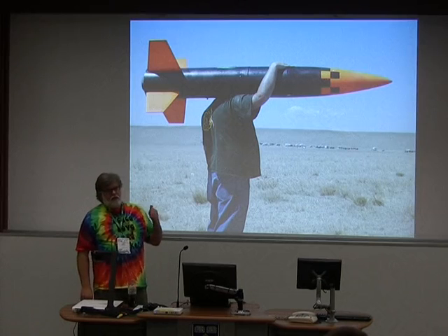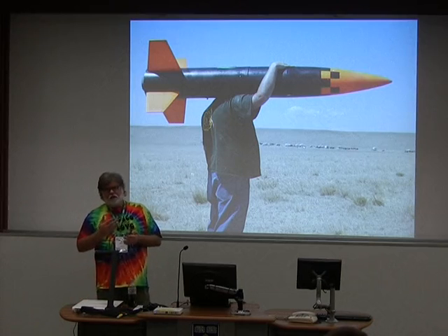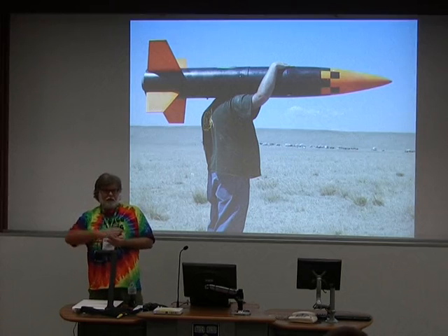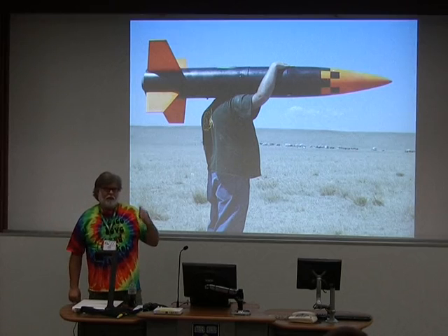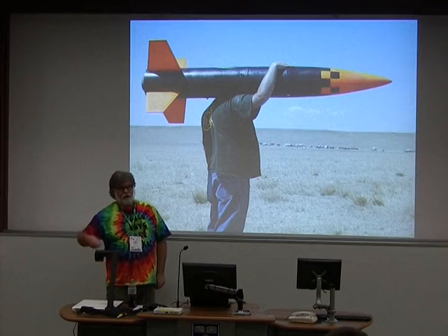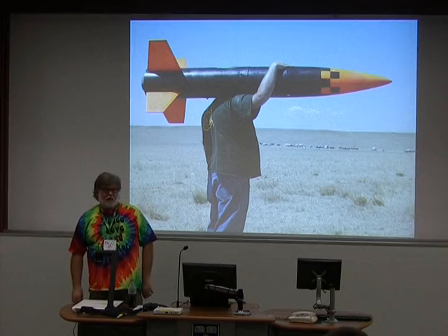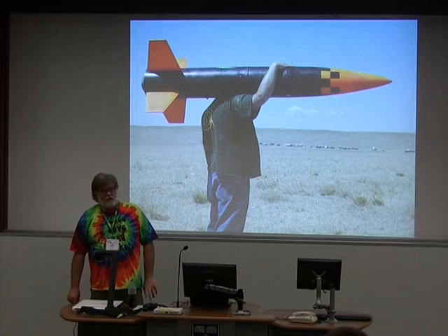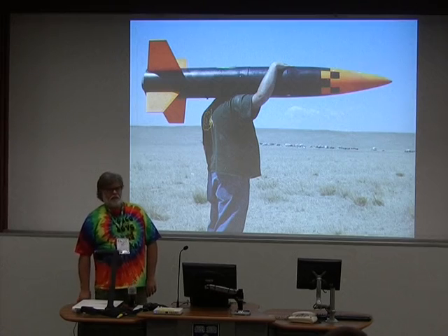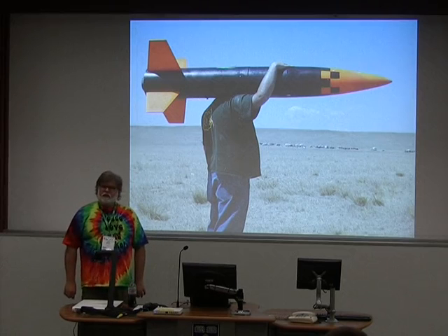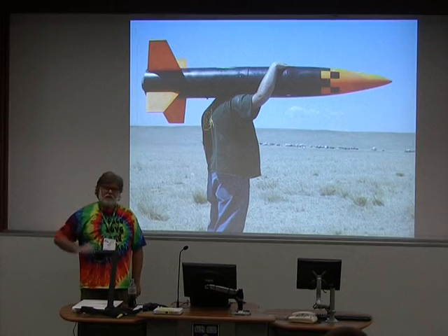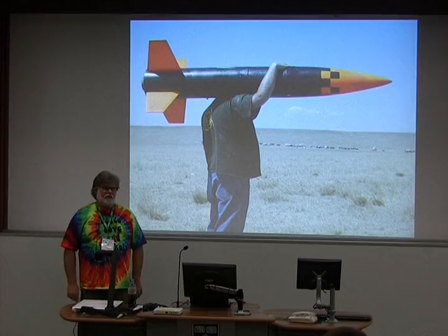It's a different thing. You have to do that, and that's 90% of the job. You have to do the other 90% of the job if you want to make something that's repeatable that you can actually just sell to other people and they'll go screw them down in their rockets, hook a battery up, go fly them and have good experiences. And that's where a lot of the time gets spent, is obsessing over the details of, we ought to pull those passives a little farther away from the mounting screw in the corner because somebody's going to whack them off the board with a screwdriver that's too big. That's happened.